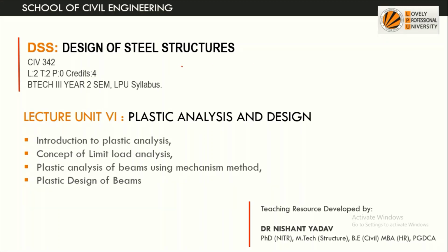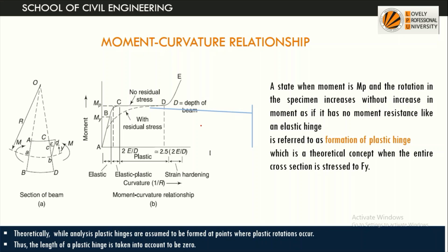So hope everybody is safe in this pandemic, and today we'll solve some of the beam problems based on plastic analysis. Just a quick recap of the concept of formation of plastic hinge, and this time we'll try to explain the same by using the moment curvature relationship.